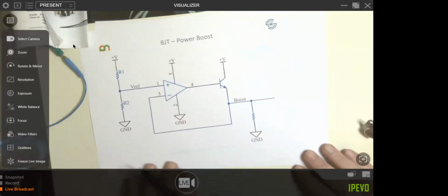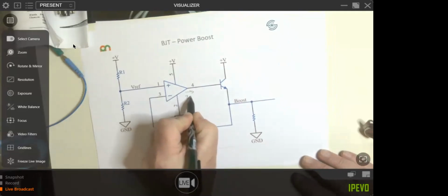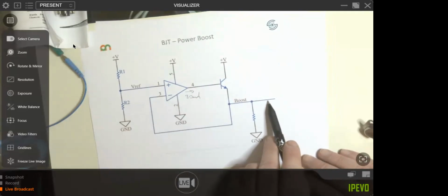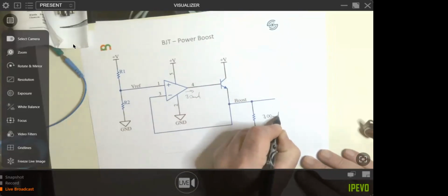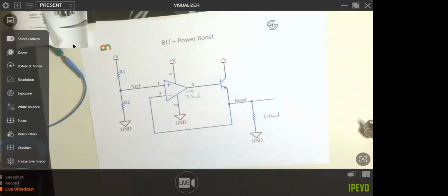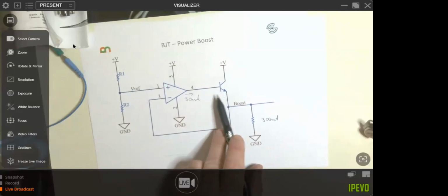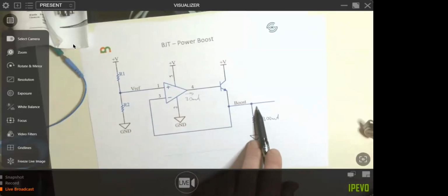For example, an op-amp might generally have a maximum current output of just 30 milliamps. That wouldn't be unreasonable. But you might have a circuit that requires, let's say, 300 milliamps. You might be driving a speaker. So we can use a transistor again to boost the currents. Obviously make sure this transistor can deliver 300 milliamps, and that's just speccing it from looking at data sheets.